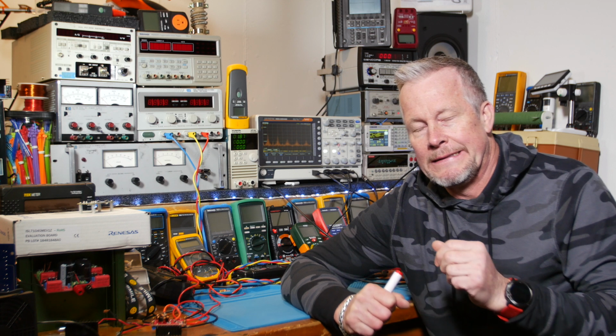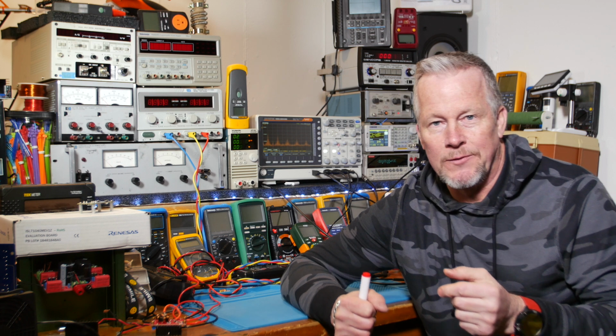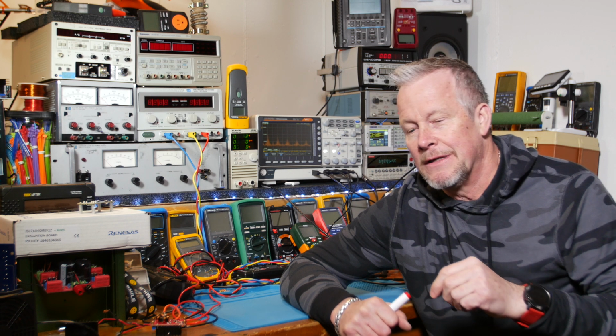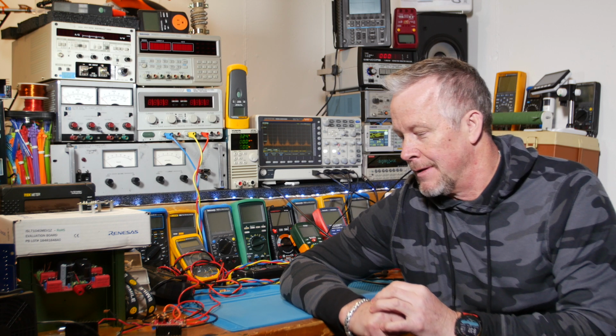On the negative side of the GaN, you don't have to have a drive chip with them, but on the drive on the gate, you just have to be very sensitive that you don't go over the voltage, like say 6 volts on them, or you'll kill them. Okay, so you just want to be very careful, and if you are switching them on really fast and turning them off real fast, going high frequency with what they're made to do, then inductance and parasitics can be important. So those gate drive chips just make it a whole lot easier to do. All right, and even with the gate drive chip, the size comparison looks great. Okay, just want to explain that.